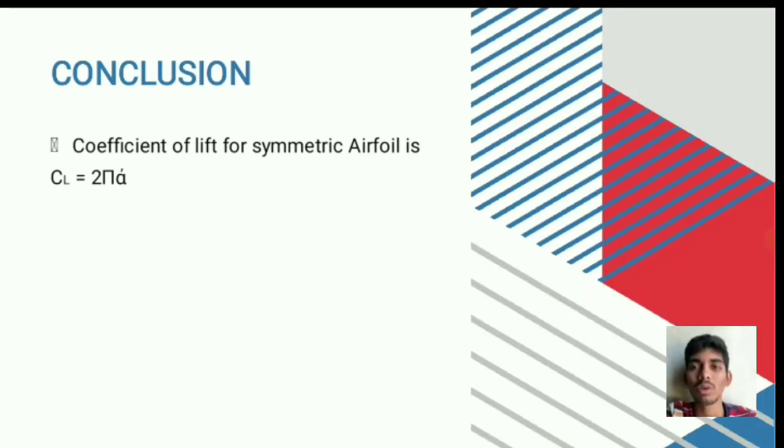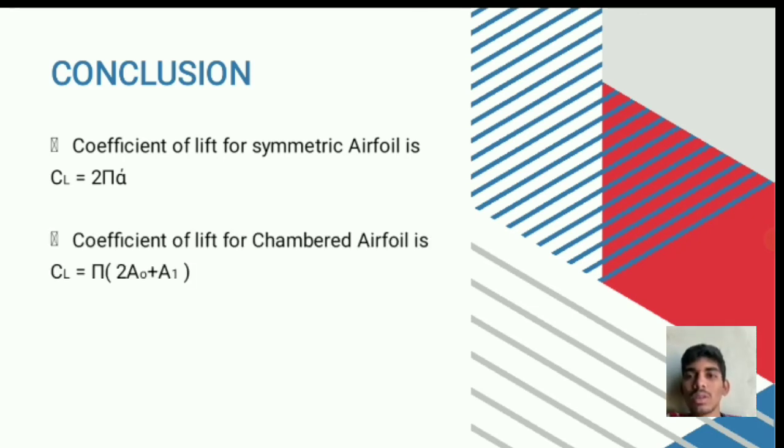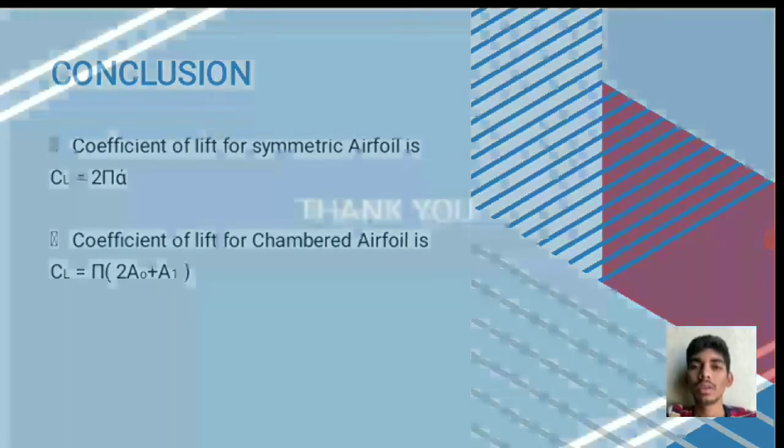Conclusion. The coefficient of lift for a symmetric airfoil is CL equal to 2 pi alpha, and the coefficient of lift for a cambered airfoil is CL equal to 2 pi (alpha plus A0 plus A1 by 2).